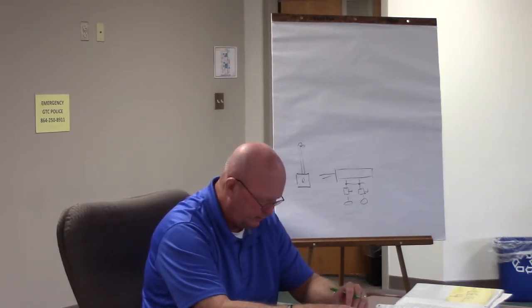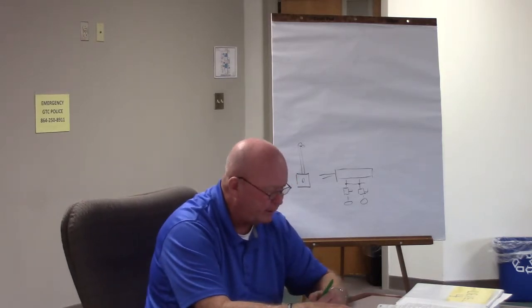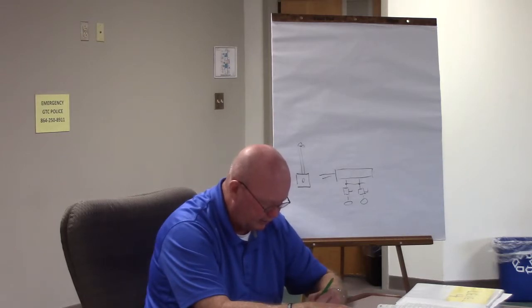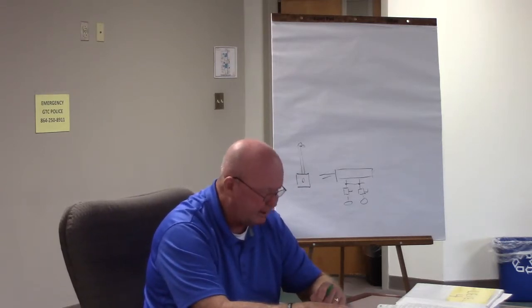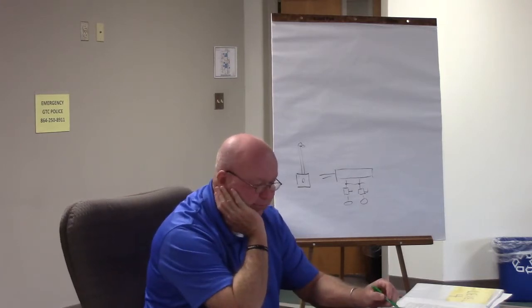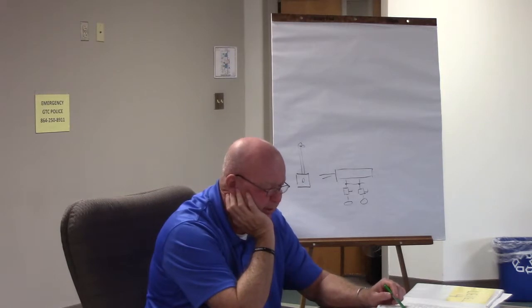Number 16. The total load placed upon certain feeders may be reduced by applying demand factors. All right, the total load, and that's found there under demand factors. So the total load placed, and it should be a D there, placed upon certain feeders may be reduced by applying demand factors. And if you look there on page 11, there's a laundry list of about a dozen or so, starting with table 220.42, which talks about general lighting load demand factors,